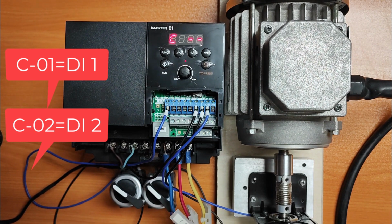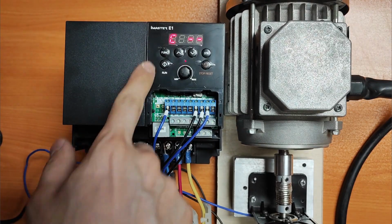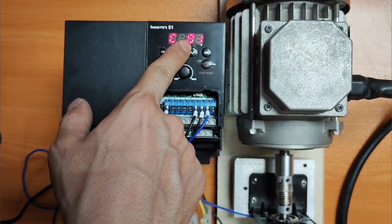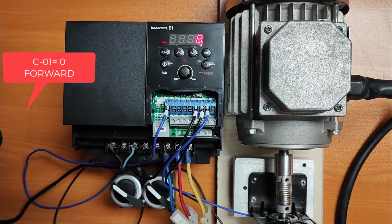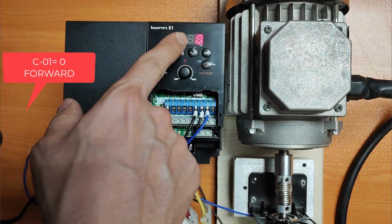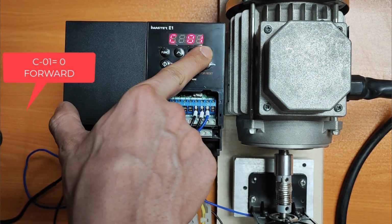We said we want digital input number 1 to be set for forward direction, and when digital input number 2 is activated, it should activate the inverter in reverse direction. Let's enter group C. Number 1 is related to digital input number 1, so let's go into it. If we want digital input number 1, when it's activated, to start the inverter in the forward direction, we need to set the relevant parameter, which is C01, to the value 0.